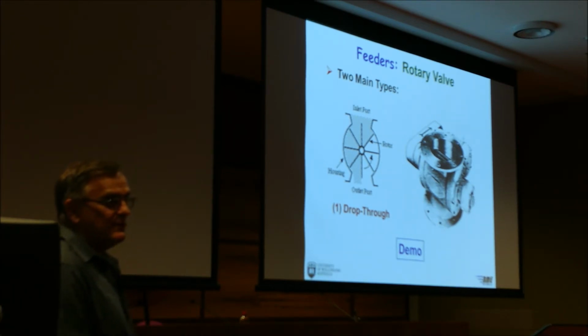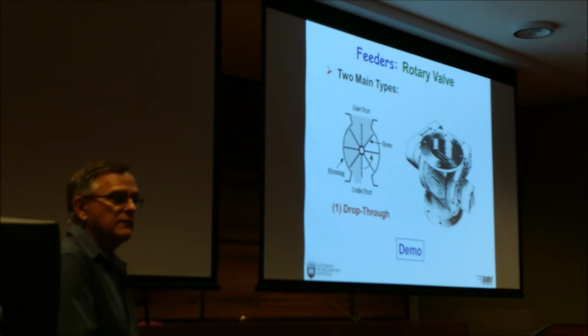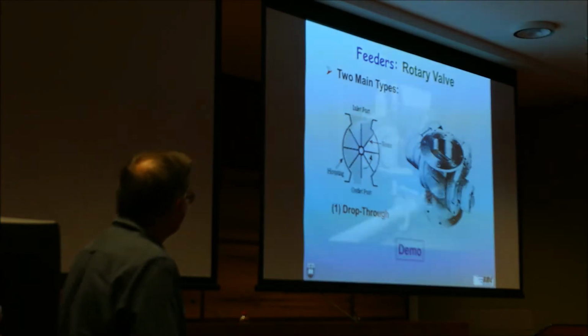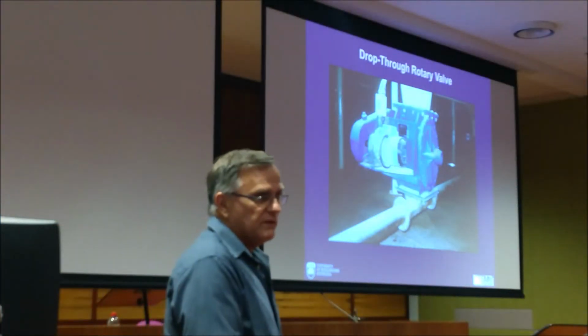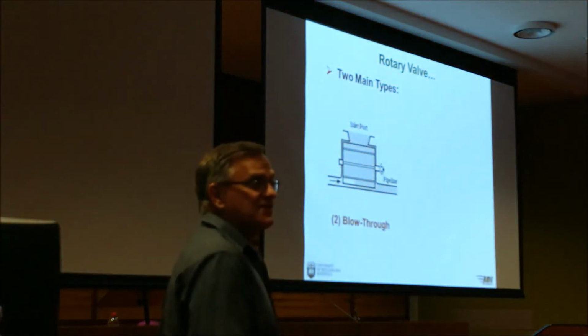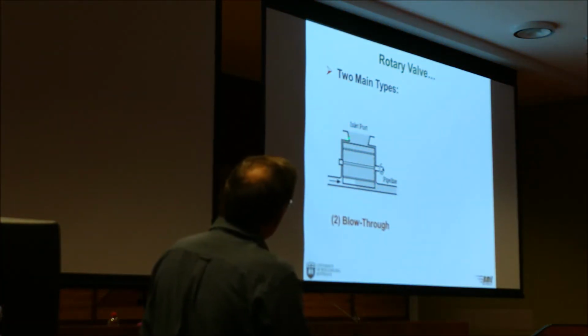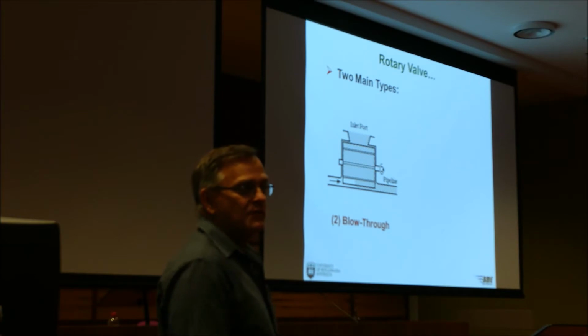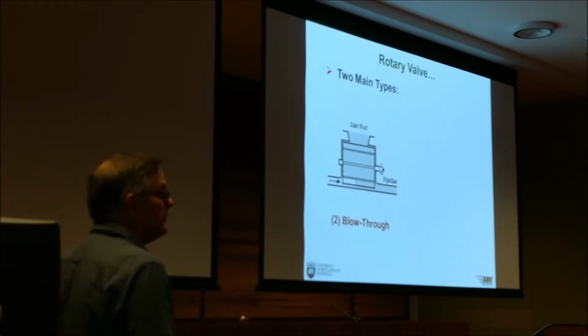I mean, some powders you throw against the wall and they'll just stay there forever. And you need a blow-through valve, definitely. But when you've got a powder that sticky, it probably builds up on the inlet port too, and chokes your valve too. That has happened.